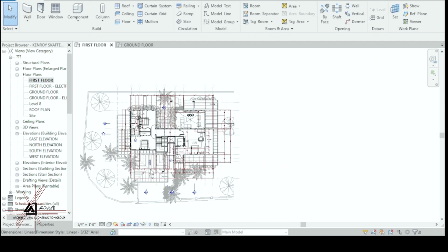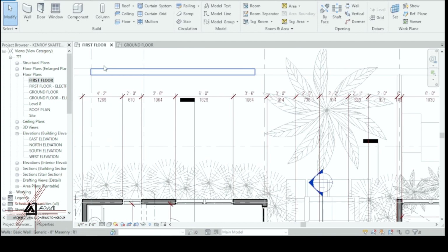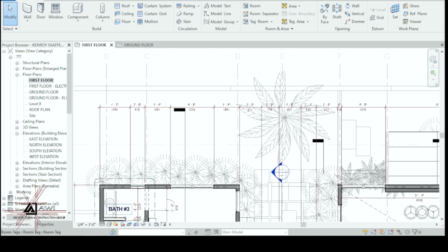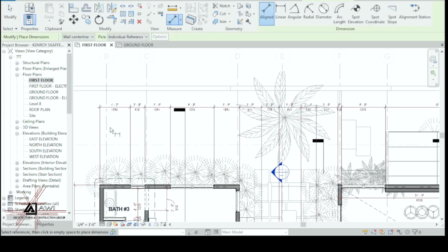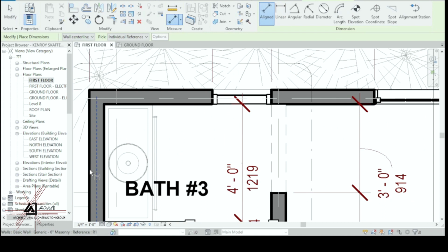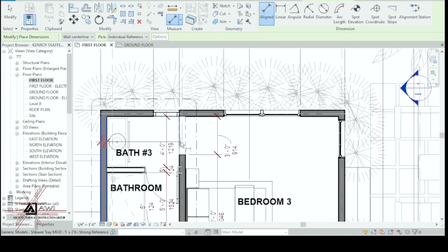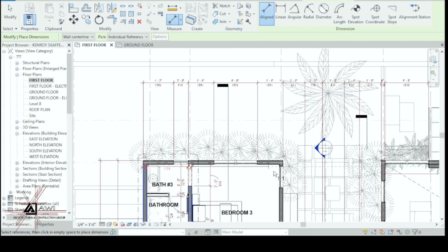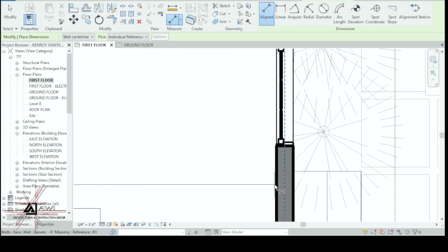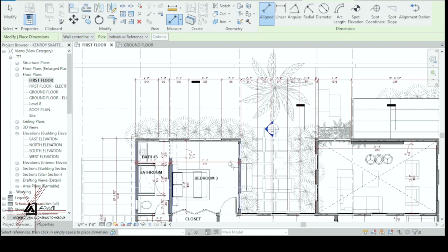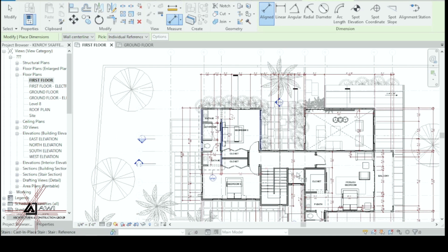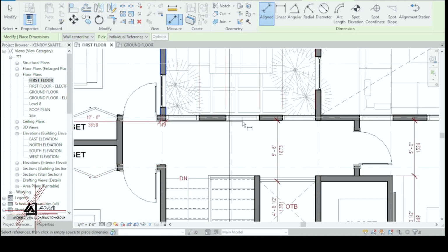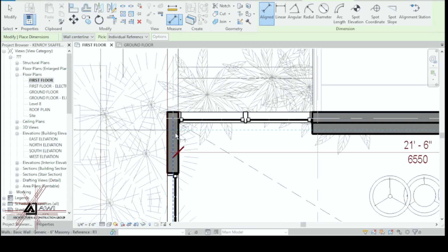Right, the next line of measurement now will be walls. So I'm gonna pick up just walls. So I'm gonna go here. This is a 6-inch wall, 6-inch wall. So it's showing the width of the rooms. This is a 6-inch wall right here. Then I come all the way. I'm not going to pick up these down here because these are not touching the face of this wall. So from here, 6-inch wall.